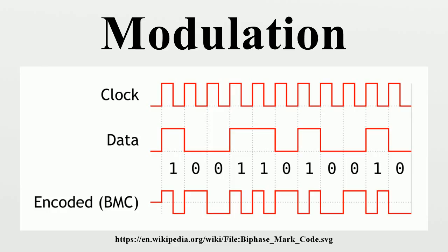If the modem plays a melody consisting of 1000 tones per second, the symbol rate is 1000 symbols per second, or baud. Since each tone represents a message consisting of 2 digital bits in this example, the bit rate is twice the symbol rate, i.e., 2000 bits per second. This is similar to the technique used by dial-up modems as opposed to DSL modems.